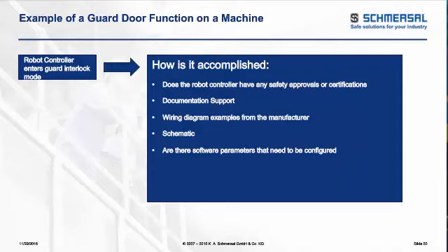With the updates and changes in the safeties with the various different robot standards from the ANSI RIA 15.06 or the ISO or the CSA standards, they've gotten more aligned and they address safety in a lot more detail and actually getting safety built into the robot controller. You can now get robots with the robot controller that has certain safety approvals already in it, and they give you the wiring instructions to safely implement a safety circuit where the robot is being integrated into.